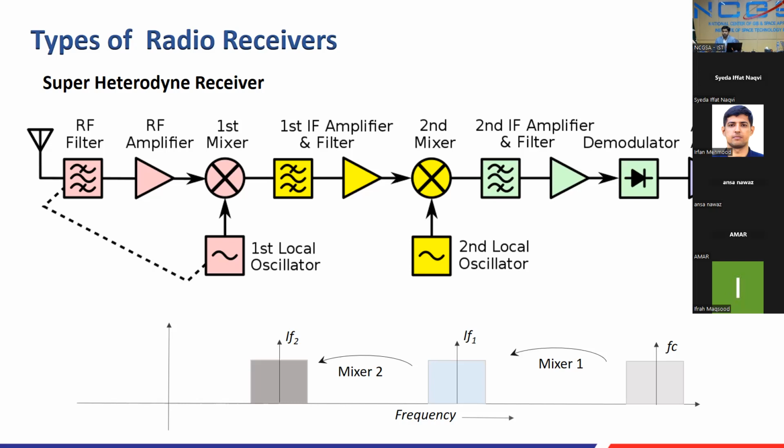This will have a high side injection that will produce a higher frequency, since you know that after mixing there are two sidebands, upper sideband and lower sideband. So you might be accommodating the upper sideband, and let's assume it is centered at 3 GHz. So this LO will be tuned automatically, then you can sweep all the frequency bands. The practical essence will come when I share the design, then you will have more understanding of the process. Then the first stage is up converted, and the second stage mixer can down convert the band of interest to an IF stage.